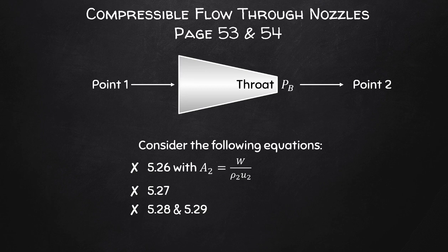While in the case where we actually reach sonic flows, P2 will typically be greater than the back pressure. It's not always the case, but usually it would be the case in terms of these sorts of converging nozzles. If we have a diverging nozzle connected to this, then this would not be the case, but we'll be discussing this a bit later.